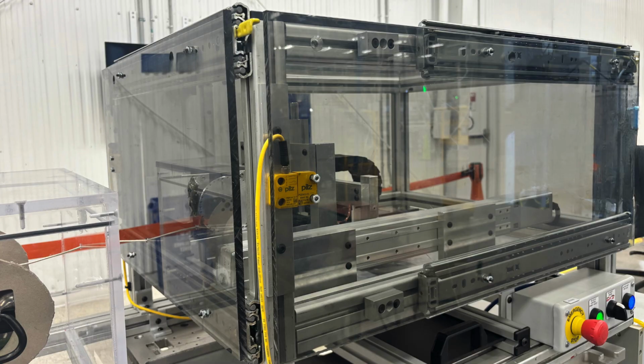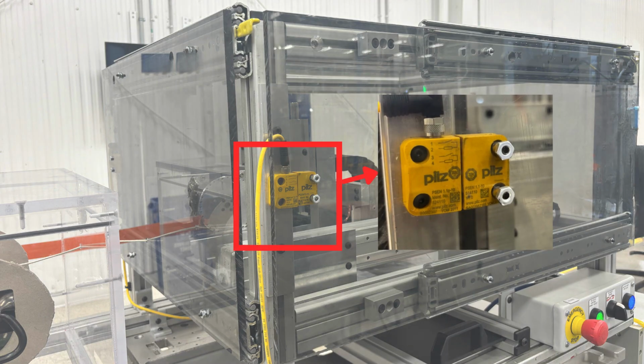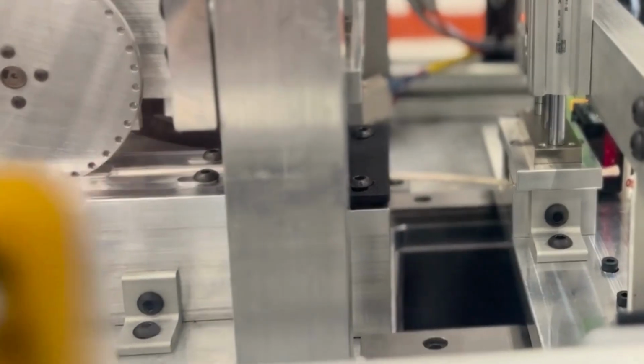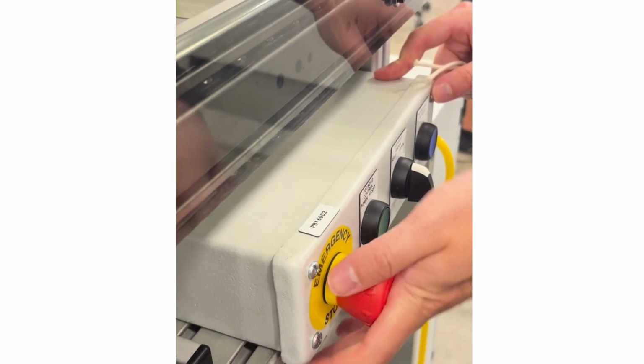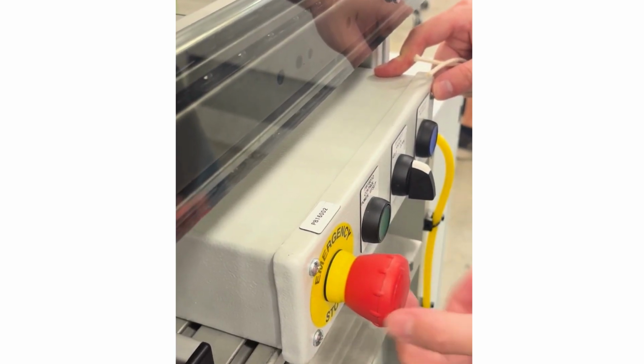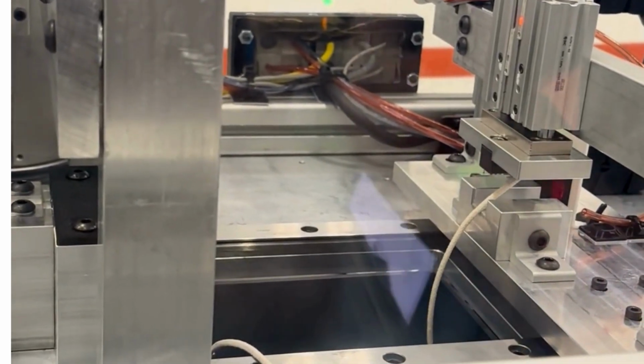Now for the safety, portability, and reliability. Safety and operational reliability were central to our engineering design. For the safety architecture, the machine is fully enclosed with a clear Lexan panel that offers toolless maintenance entry while protecting the operator. All access points are fitted with the safety switches tied directly into a dedicated safety relay. Opening any panel breaks the safety interlock, preventing machine operation. An e-stop button instantaneously removes power and halts all system motion in under 2 seconds.